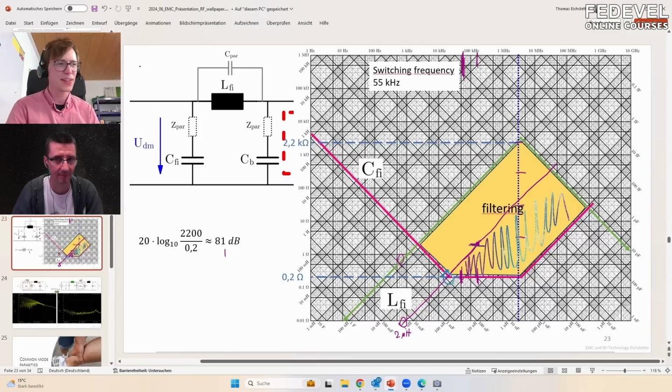I had a company where there was such a high current because of this effect that the coil itself was soldering out of the circuit. Really? So it really is important what kind of capacitor you use in this filter, because kind of by accident you can create a filter which is resonating at the switching frequency, and then this is going to be a problem.